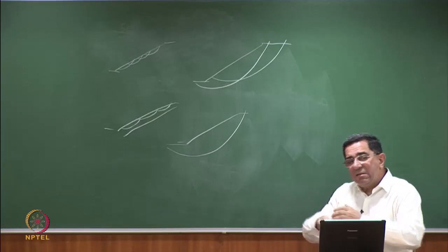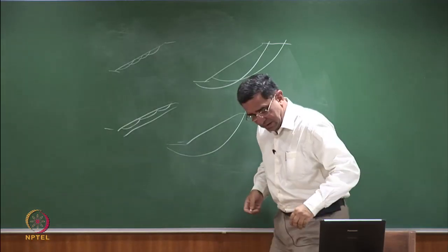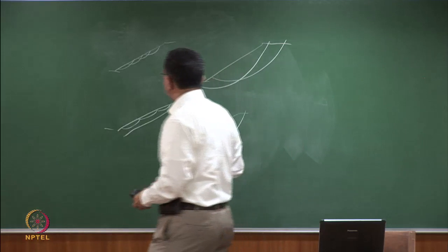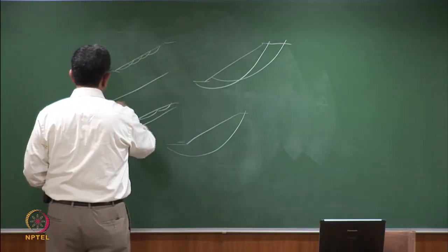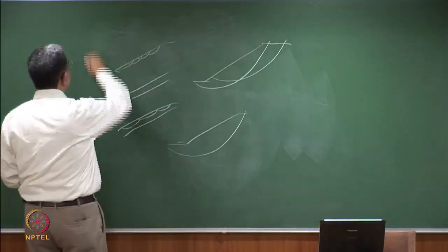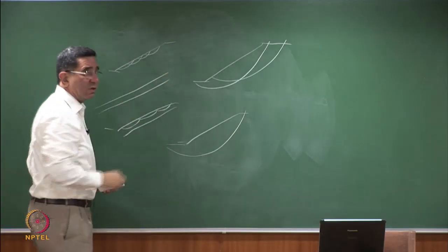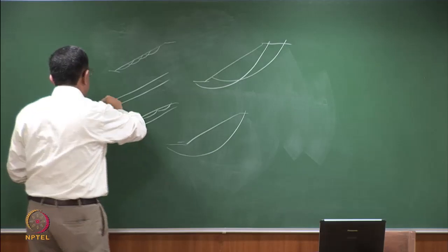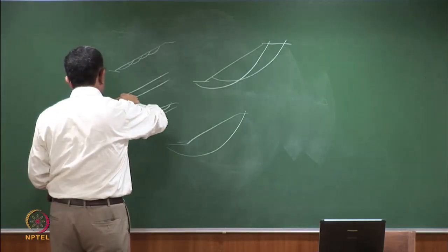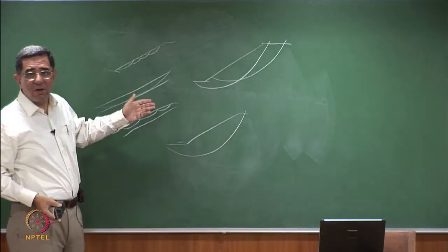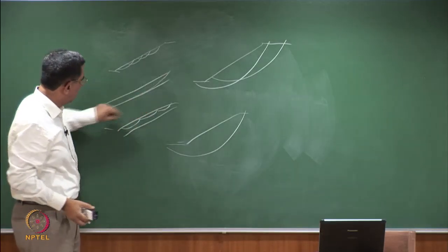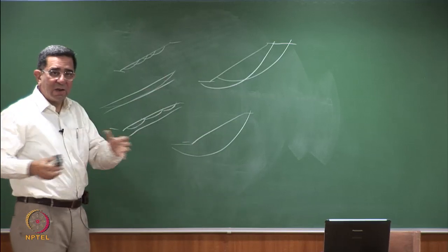So when I increase the radius very high, I just want to finish this issue that this is my limited depth to which the failure can take place. I can put my center of rotation very far. When I put my center of rotation very far, then it's almost a failure surface parallel to the outer slope. These two edges are too small.